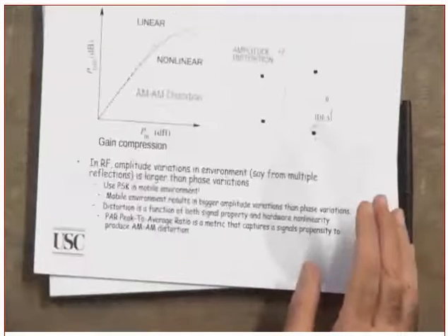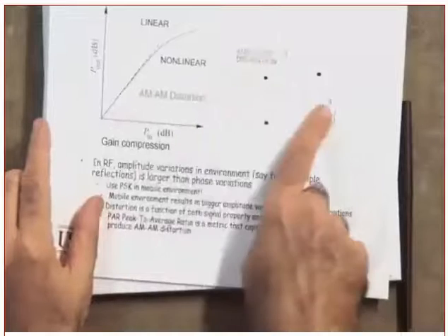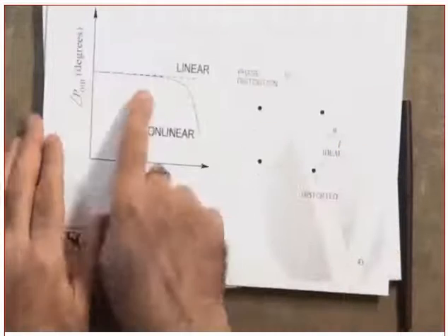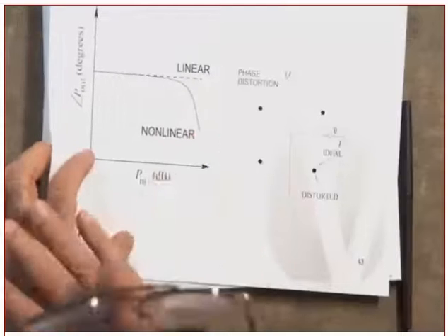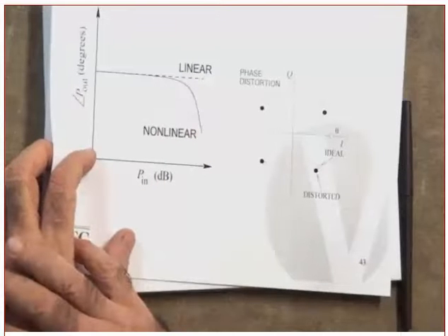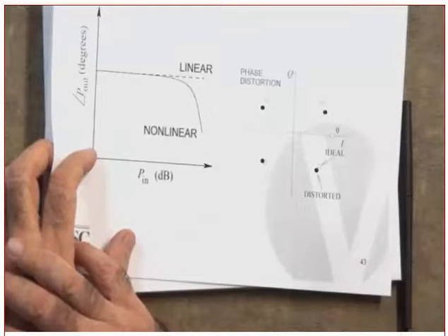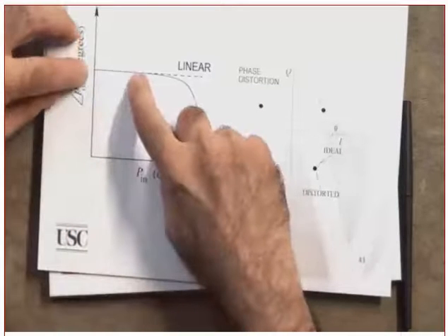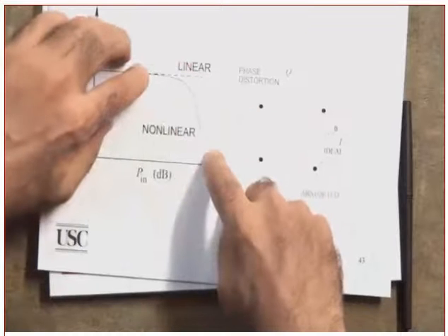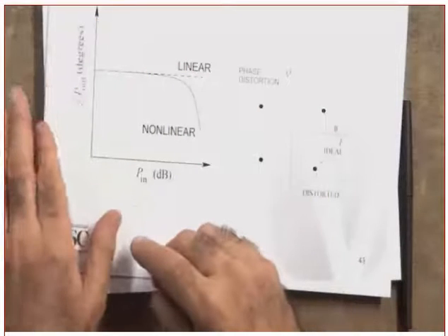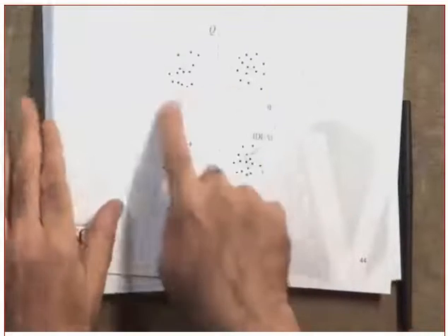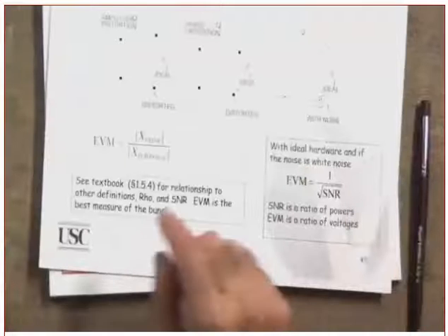Now, the amplitude could also get distorted. You see this one, different amplitudes. The phases could also be distorted due to the nonlinearity. Remember, for the system not to introduce any phase distortion, the phase characteristic should be linear, passing through the origin. In here, this is linear. But once you get into this region, the system fails to be linear, introducing all of these phase distortions. Noise is all over the place. Clear? Oh, the parameter of interest.